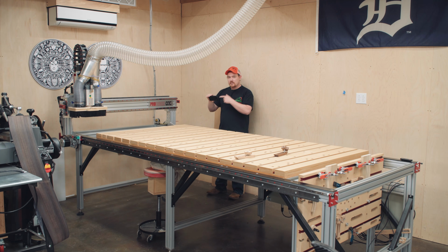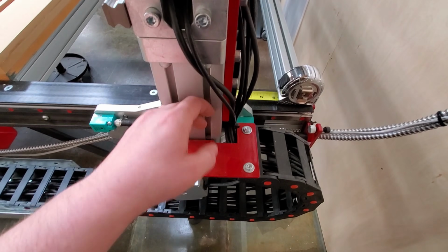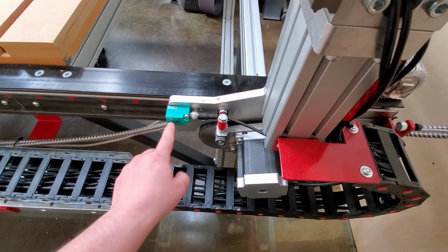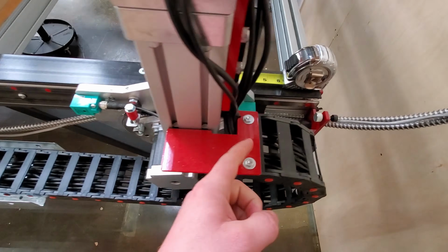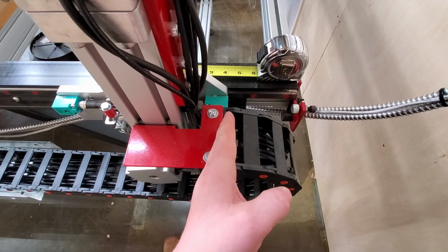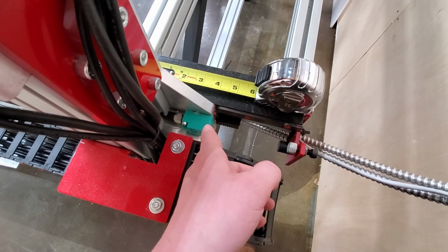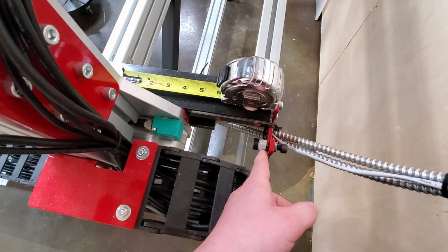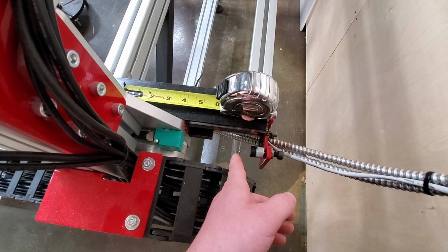So I'm going to switch over to my cell phone because I can't get that camera back here, and I'll show you exactly what I'm talking about. So over here on this gantry post, there's this limit switch which stops in that direction closer towards 0. And like I said, the machine just stopped at 120 inches, but as you can see, there's still some more space between that limit switch and this end stop. So we can figure out how much more space and change that value in the computer.